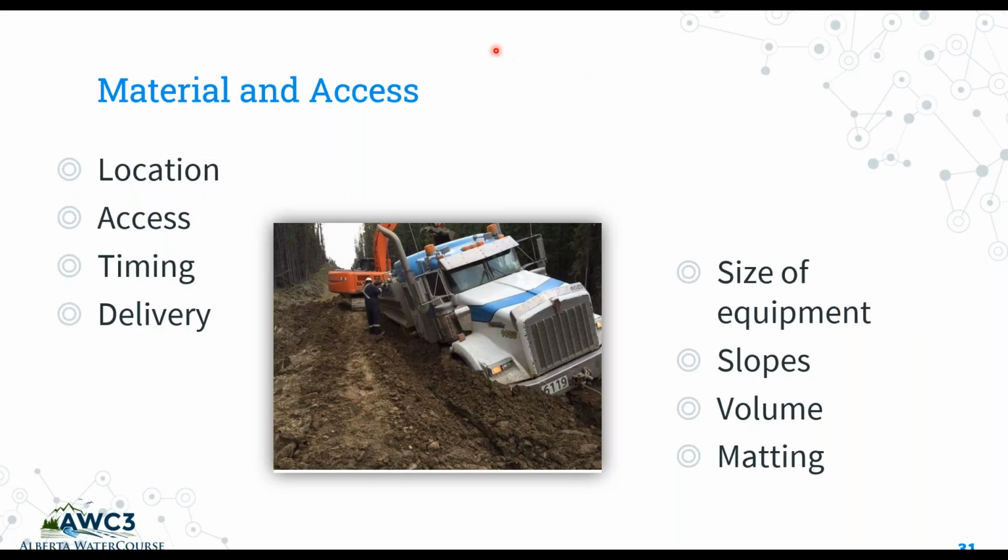Materials and access. If you are working on a crossing where you're going to be bringing aggregate in, or bridges in, or trees for your slope stabilization, you'll want to think about: is that on site ahead of time? How do we get at the site? What time do we need it? How are we going to deliver it? Are we using the right size of equipment? Do we have steep slopes going into the site? What's the volume of material that we need to bring to the site? Do we need access matting to access the site with this equipment?